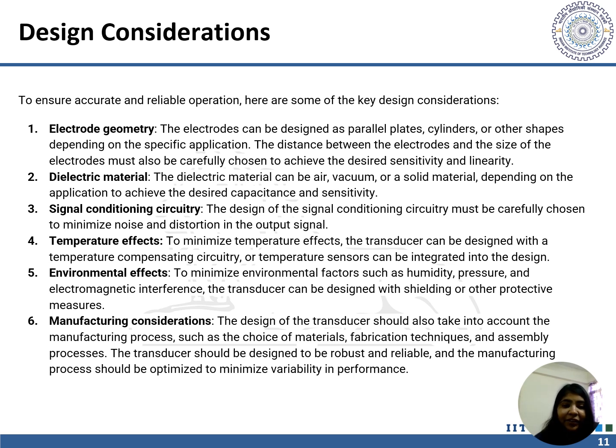Second is the dielectric material. As I mentioned previously, it can be air, vacuum or any solid material depending on the application to achieve the desired capacitance and sensitivity. The third consideration that we make is in the signal conditioning circuitry. The design of the signal conditioning circuitry must be carefully chosen to minimize the noise and distortion in the output signal. The fourth is the temperature effect.